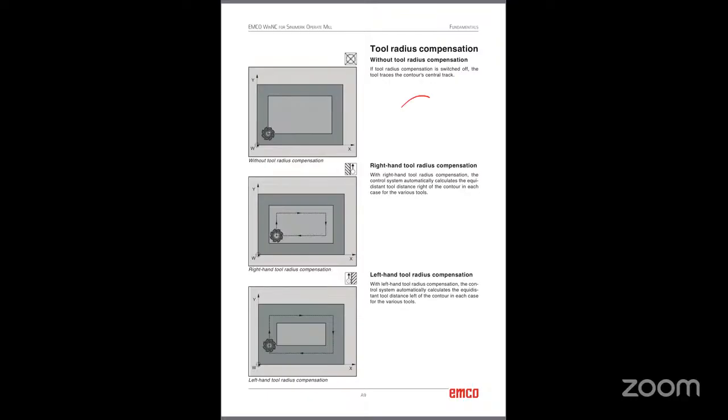So for example, we have a milling cutter, an end mill of diameter 10. That means the radius is equal to 5. So when the tool is moving, the tool center is moving. If we do not consider this radius when we write the program, this much portion will enter into the workpiece and remove the material. So compensating for that radius is what is called tool radius compensation.